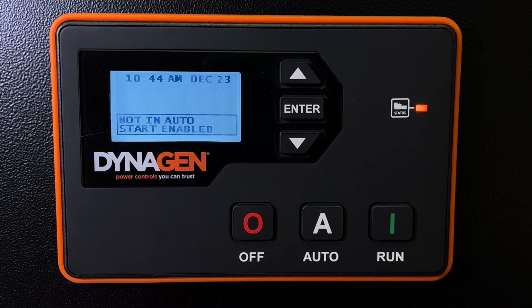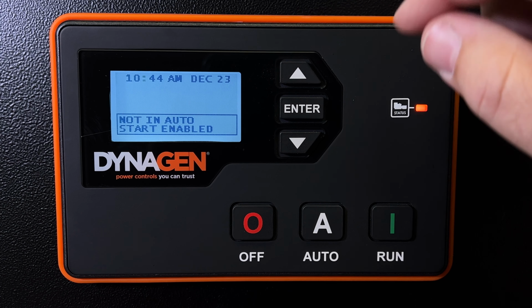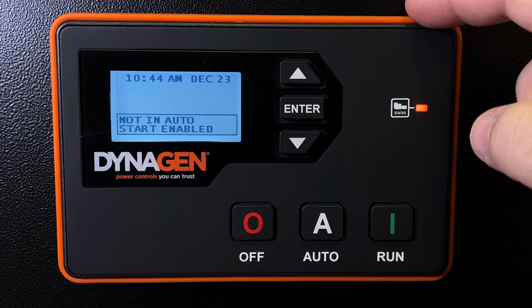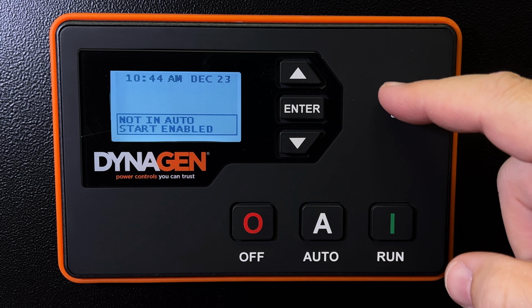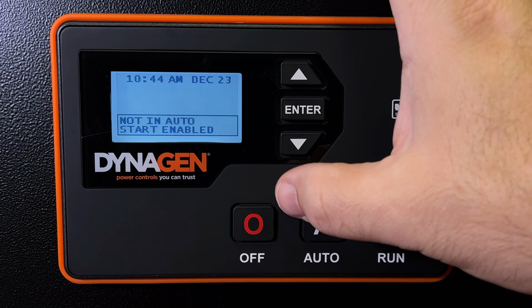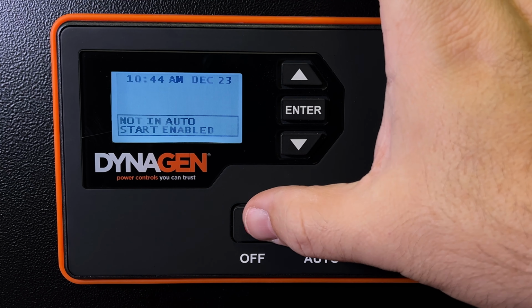And we're back at the DynaGen TG410 controller, or the TG350 controller, depending on which Aurora generator you have. Just wanted to show you some configuration settings here on the switched inputs on this controller. For automatic generator starting, we use switched input C on this controller. It's got a bunch of inputs, and one of them is labeled C. You don't have to worry too much about that, but I just wanted to show you something here.